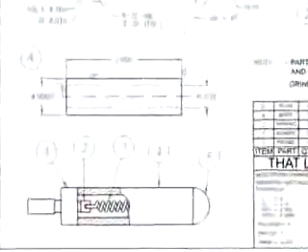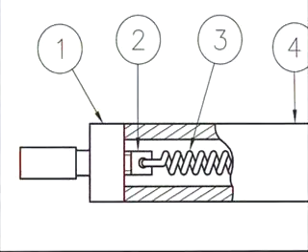Here is a really informal type of section. I wouldn't even call it a view. It's more just a window to the inside of a part. I call them broken edge sections, and they are generally found on assembly drawings.